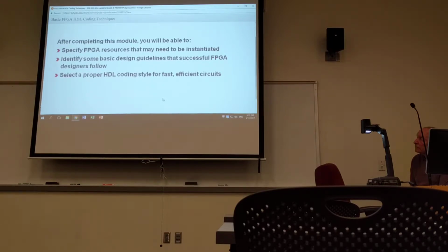The bottom line is that all the high-end synthesis tools available for the FPGA industry usually do not allow inference of all the best FPGA resources. That is usually the latest and greatest, like the DSP slice and block RAM resources. Now, synthesis tools may allow some inference of these resources. There are plenty of exceptions, but usually only primary applications are inferable. For example, the block RAM resources are inferable for memories that only use a single block RAM, are not initialized, and don't use the output register functionality.